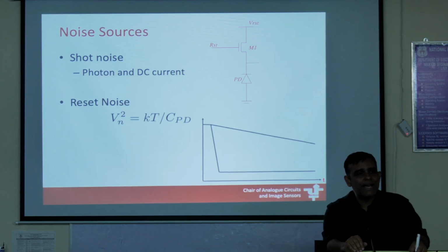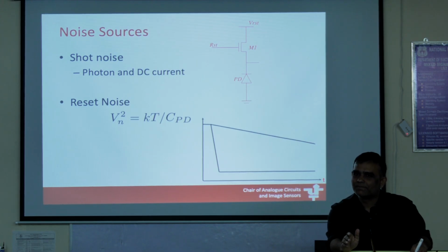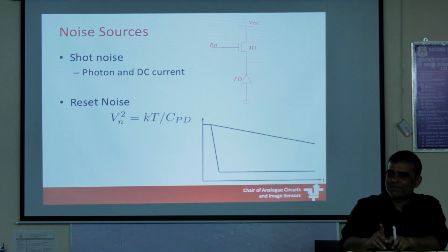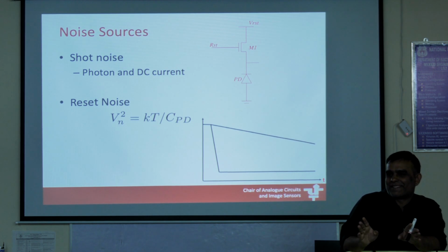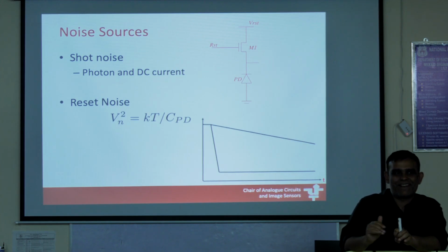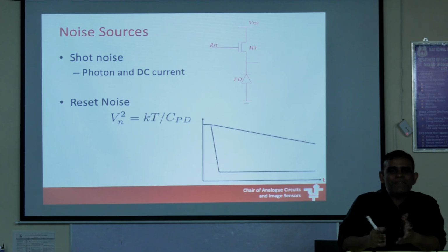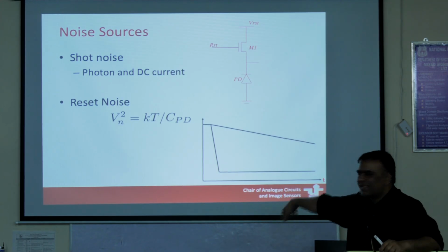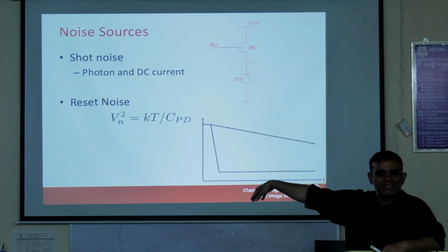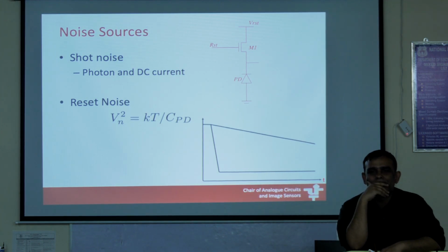The other thing which we have is, we are not very high frequency people. I think one of you teaches RF circuits or works on RF circuits. At RF radio frequencies, you ignore flicker noise completely, as if it doesn't exist. It's 1 over f noise, and the frequency is high. We are not high frequency people. What is going to be my T? Remember in these equations we had a T, the integration time. What is that going to be for me?